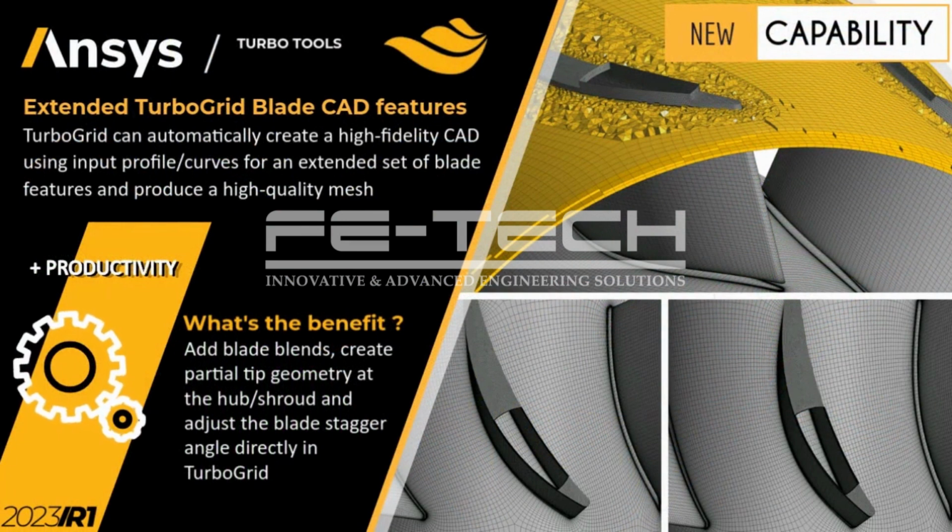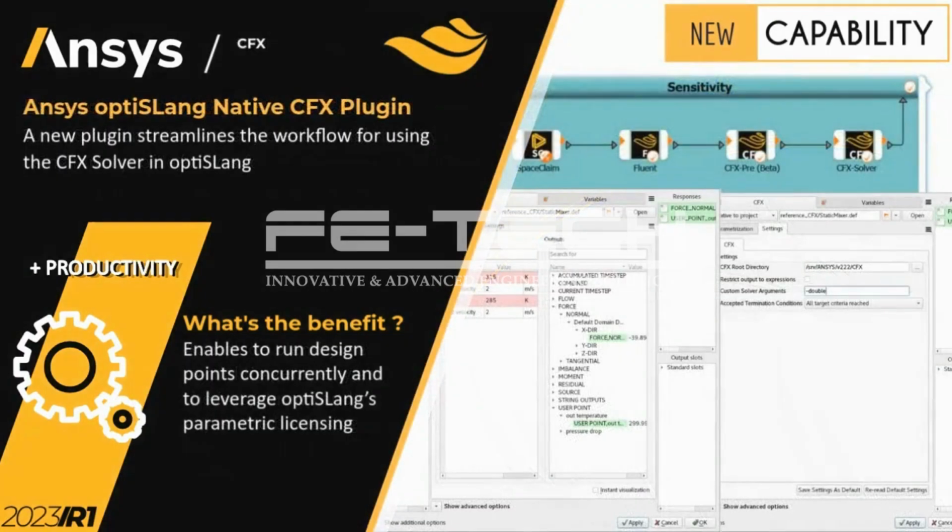You can now add blade blends, create partial tip geometry at the hub and shroud, and adjust the blade stagger angle directly in TurboGrid. You can use profiles and curves as input geometry, and then TurboGrid will automatically create the high-fidelity CAD with the additional blade features and produce a high-quality mesh.